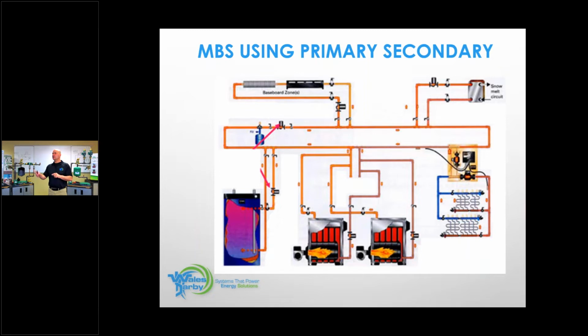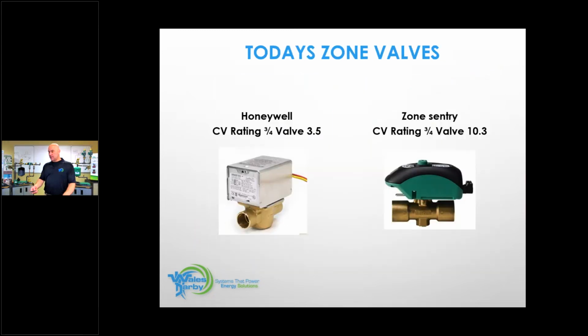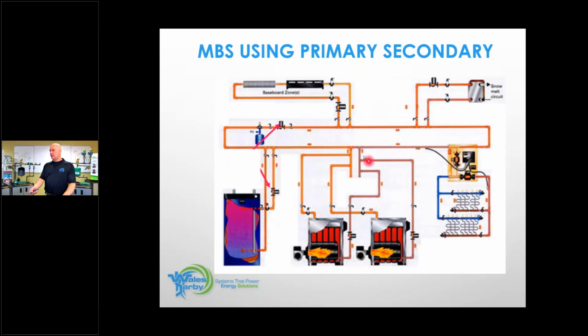Anybody have any questions? One question that came in is, Jim is asking, is it a monoflow? Is that a monoflow? No, that's not a monoflow. That is just closely spaced tees. Each circuit has its own circulator with a dedicated flow. And this circulator has very little head restriction, but its goal is to support the total volume of gallons for all of the heating coming off of that hot circuit.